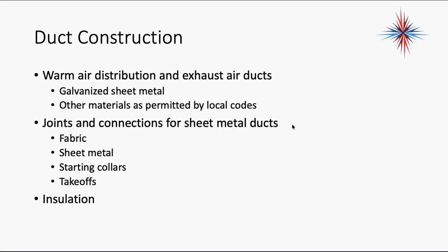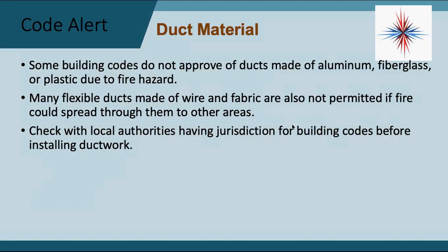We do that with what's called a duct blower test. We pressurize the ductwork and measure how much air we have to continue to put into the ductwork to maintain the pressure in the ductwork.